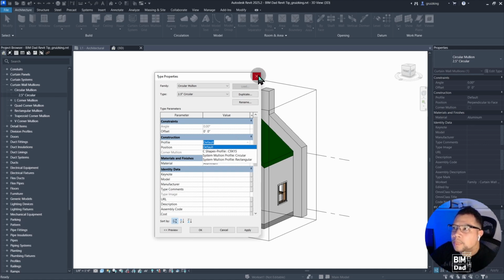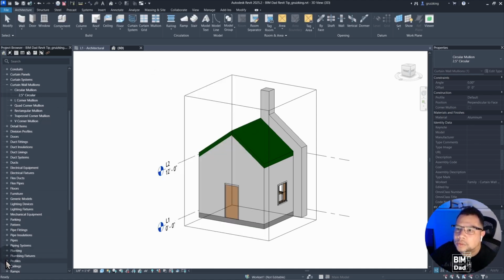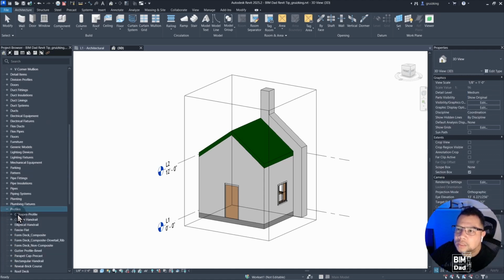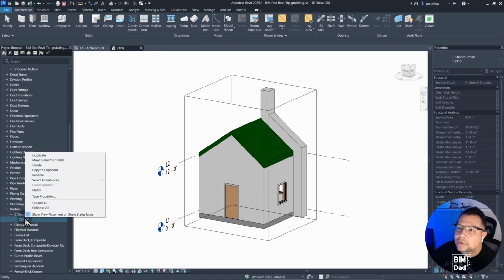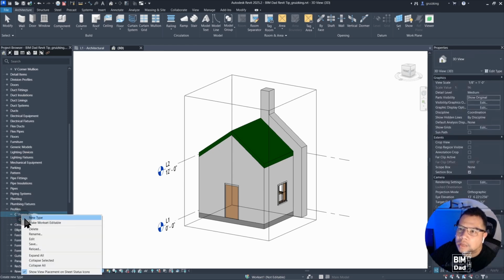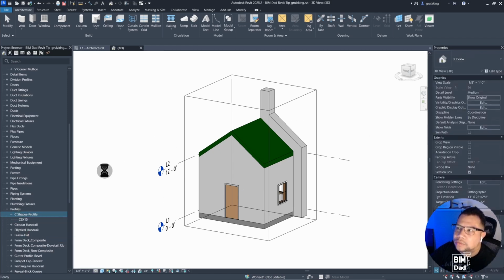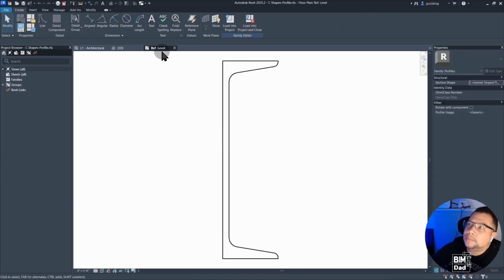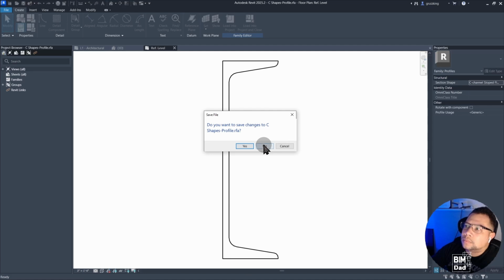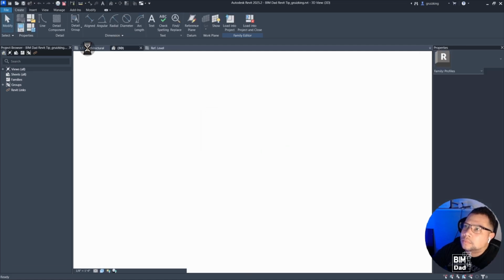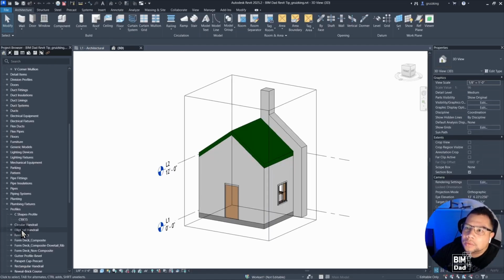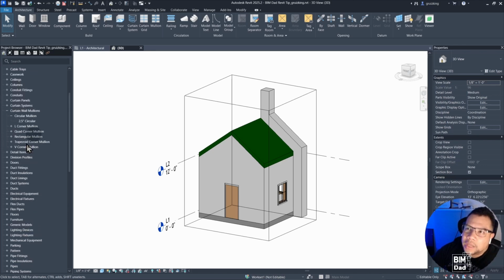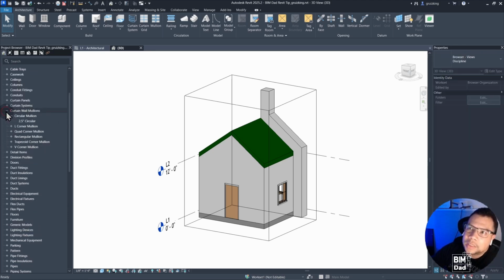The C-shaped profile. I close that and I go down to profiles, we'll see the C-shaped profile and just that one loaded. Now, if I right click the main name, I can edit this outside of the Revit project, which makes it a loadable family. So going back to the model, that's one atypical system family that looks like a loadable family.